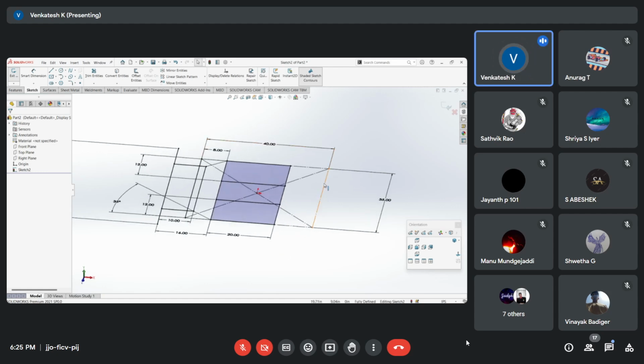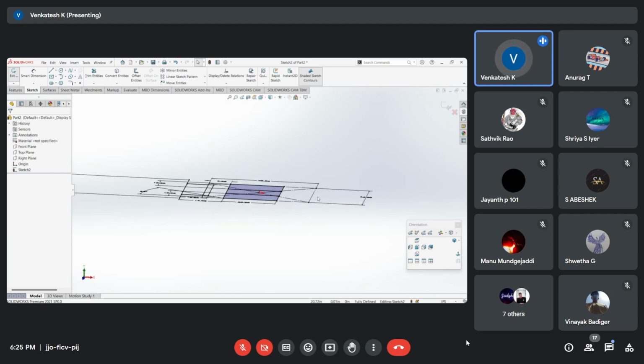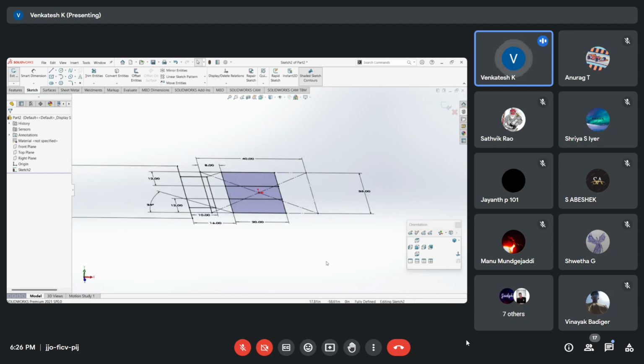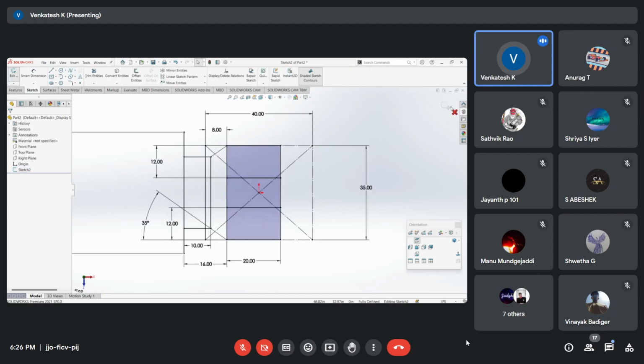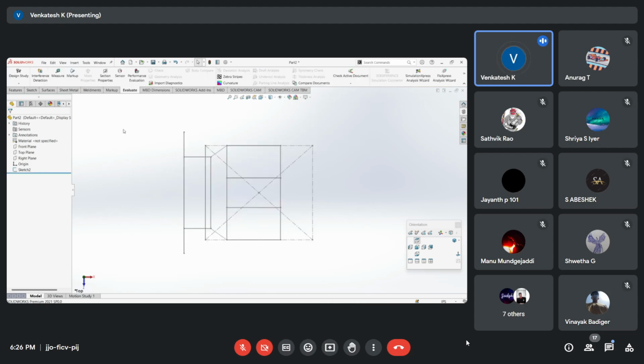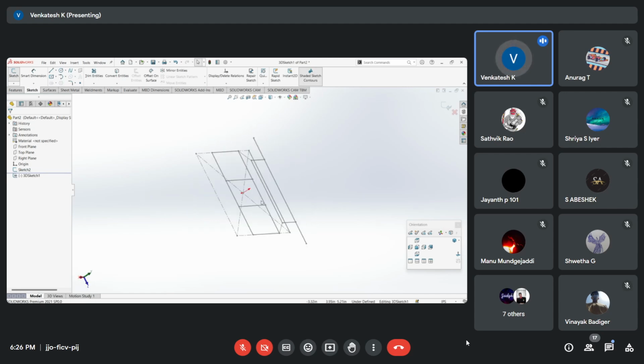Since the stub axles and the Pitman triangle and the rods will be in line with this chassis, we need to elevate the frontal portion a little bit. We'll do that by using 3D sketching. For that, we'll have to get out of the first sketching. You get that option there. You get out of the sketching and go to sketch. Under the sketch, in the drop down, you get 3D sketching. 3D sketching is not that convenient, but we can use it.